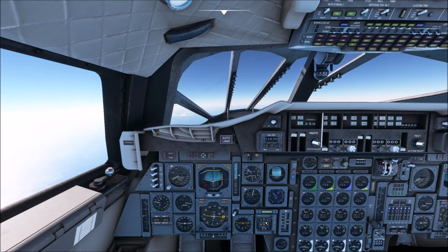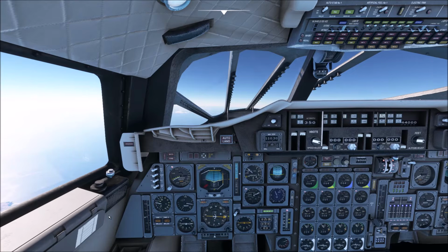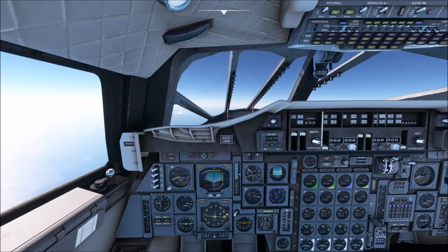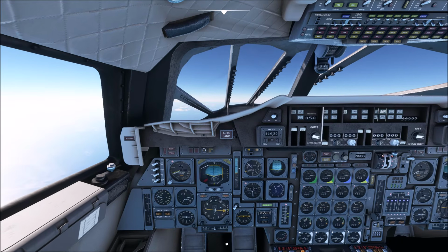As you can see, we're 25 minutes into the flight. This is actually quicker to altitude than real life, because as I say, Concorde would have waited to get over the Bristol Channel and it would have done a shallower climb, probably only 1,000 feet a minute. Nice low throttle setting, 400 knots maximum, and then arrived at the Bristol Channel right on 24,000 feet, ready to accelerate supersonic, and that would have saved some fuel. So we're doing it a little bit inefficiently here just for the sake of the video, at a much higher climb rate out of Heathrow.